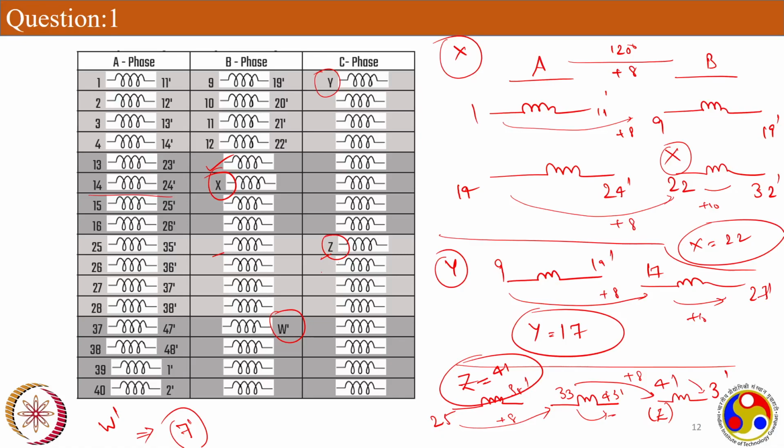You want to calculate that. See, if you want to calculate the voltage, you need to understand it in terms of actual numbers. If you want to calculate that, it's not possible. Like if you want to see the current flowing, you need to get the winding resistance and multiply it to get the voltage. But if you want to calculate in terms of voltages, like E1 dash, E1 dash, in that terminology, you need to see how you are adding these coils within the coil group. Now there will be a resultant phasor. See, you just have to assume if it's a plus, and all these will be plus under this pole.